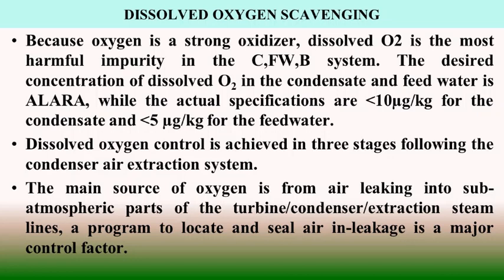Dissolved oxygen is removed from the condensate by the deaerator, which contains a spraying arrangement and cascade trays over which the hot water is sprayed, and there is pegging steam supply through which oxygen is removed, and through a vent condenser it is disposed.